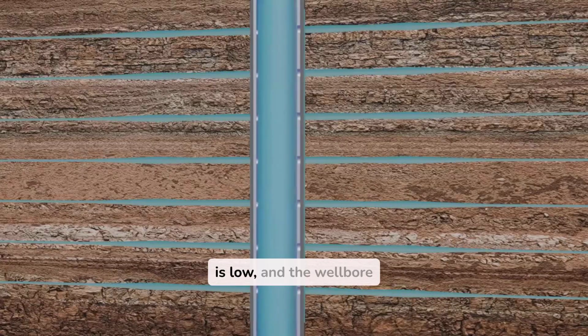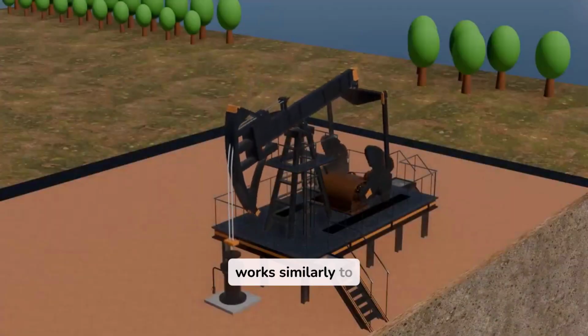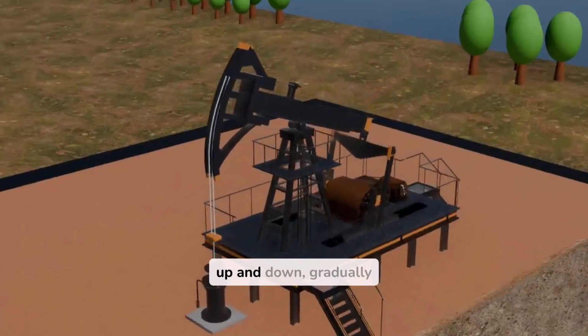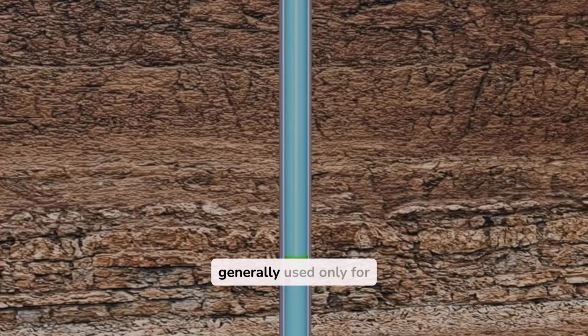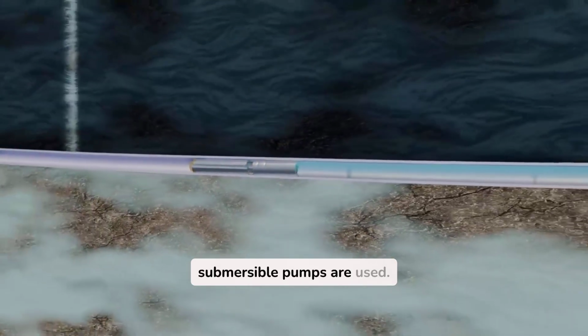However, if the pressure is low and the wellbore is around 500 meters deep, a beam pump is used to lift the oil. This works similarly to a large hand pump. A motor drives the beam up and down, gradually pushing the oil upward step by step. Beam pumps can extract around 50 to 500 barrels of oil per day, and are generally used only for onshore wells. For deeper wells or those with lower reservoir pressure, submersible pumps are used.